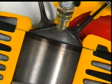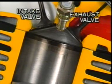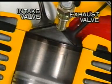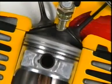The cylinder head of the 4-stroke engine has an inlet port and an outlet port. Each port is equipped with its own valve. These valves are operated by the camshaft, and they open and close the ports to effect intake and exhaust. This is the main characteristic of the 4-stroke engine.